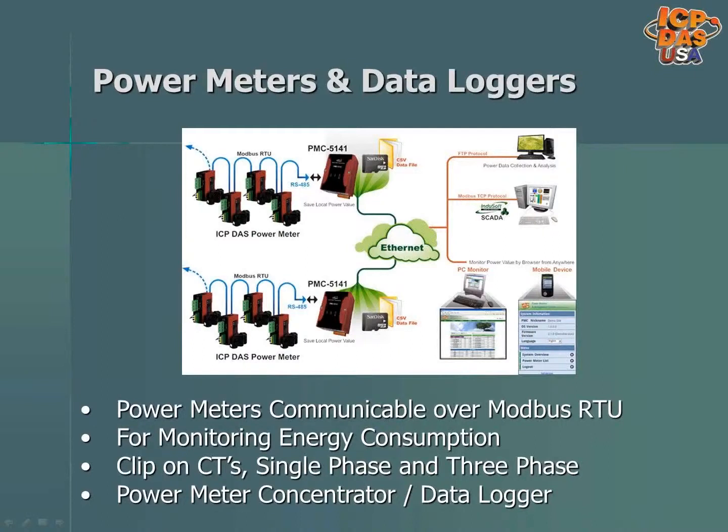Energy management systems help with monitoring power consumption and usage. Monitoring energy can help you save on costs, since changes can be made to reduce energy usage when it's not needed. SCADA control and monitoring software can be used to display the data in a way that's easy to understand and analyze. We provide Modbus RTU-based power meters that can be used to gather kilowatt hours and energy consumption data. You can daisy chain many power meters together over the RS485 bus, and you can send the information back over the internet with cellular modems.